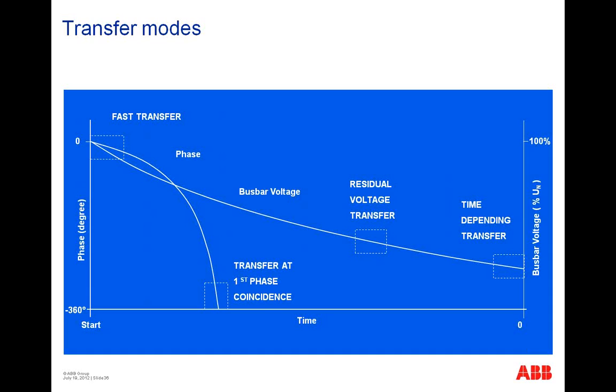We want to close the breaker at the moment of absolutely synchronous condition, so that you have a very smooth transfer without a big inrush current or anything else that would cause a mechanical torque hit on the motors. Then the residual transfer, if this is not possible, is like a backup, for the last possible case, failure in the main incomer and also blown away.